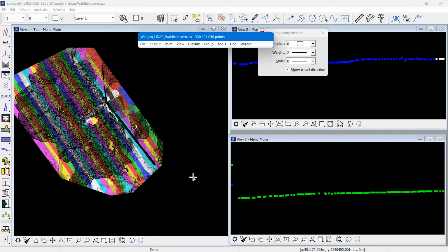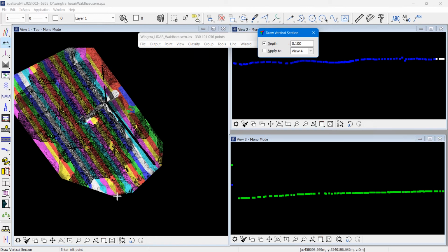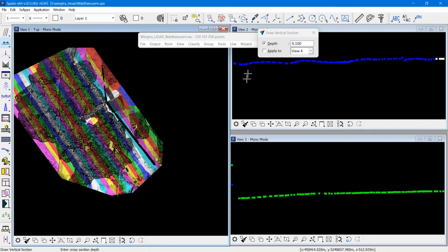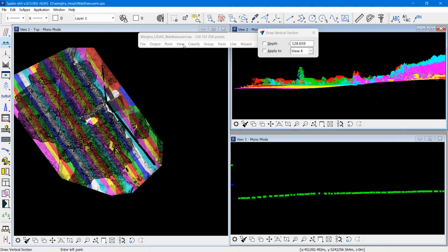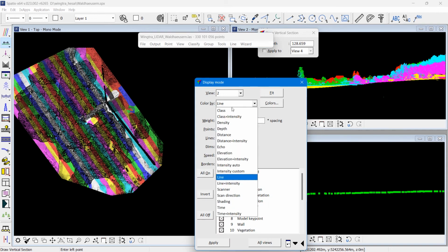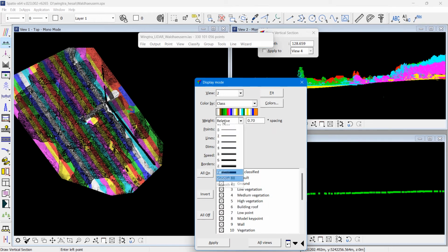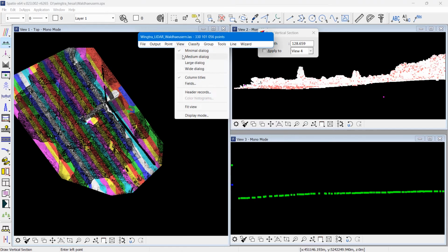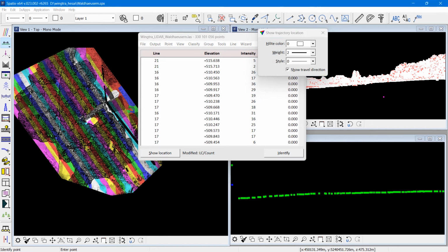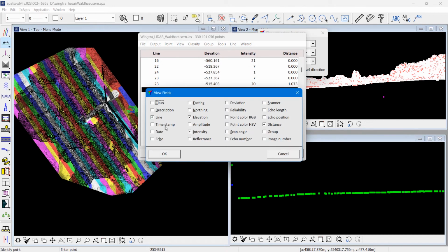So now the smoothing is done. The laser data looks cleaner in a cross section on a hard surface. And some points have been classified as low points. So now the point or the points in here are in class 7, low point class.